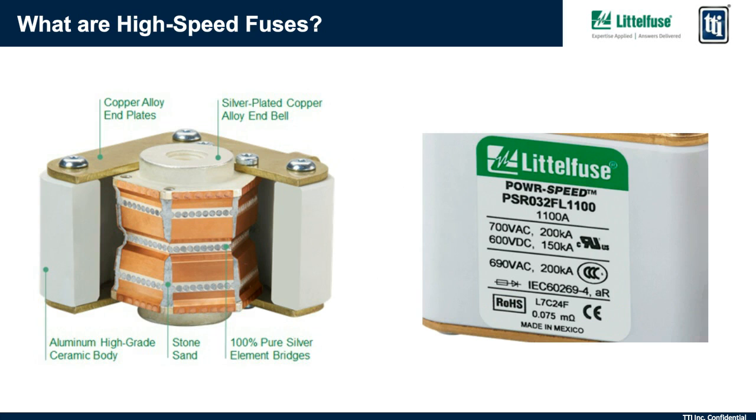So if we take that fuse and we look at how that fuse is different in the internals and also just on the information provided. This is a cutaway of what we call a square body high-speed fuse, which is our fastest fuse. And the different components help that fuse to be as fast as possible, breaking down from the pure silver element bridges and the stone sand for faster quenching of arcs, and also the ceramic body that has to do with heat dissipation.